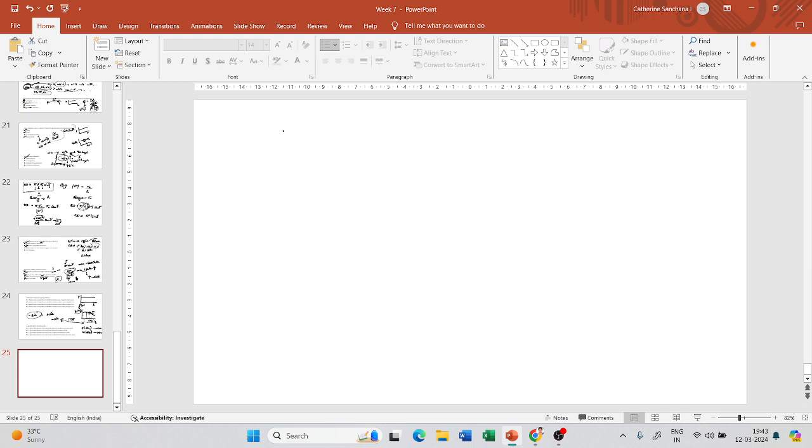So low temperature cracking and fatigue cracking are kind of similar, except that low temperature cracking has the influence of temperature and the number of repetitions of load, whereas fatigue only has repetition. Now, what did you do for fatigue cracking? You gave a maximum value, right? Maximum 6000 kPa. So if it goes more than this, it is prone to fatigue cracking. As I said, low temperature cracking and fatigue cracking are more or less similar.